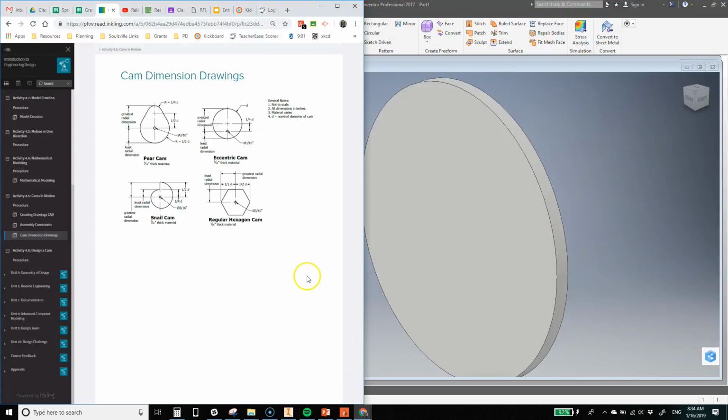And let's look at where that's going to be. So my hole should be halfway between the center of the circle and the outside edge. So that's about 1/4 D. Because my diameter is 4 inches, this distance for me is going to be 1 inch. For you, it's going to be 1/4 of whatever your diameter is.